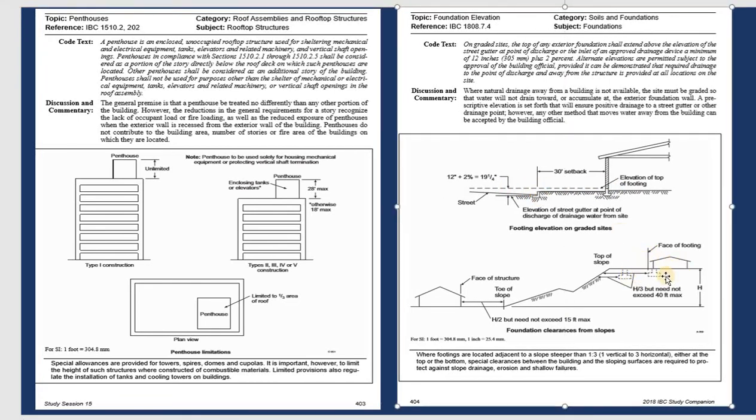If you have the house and face with the footing look like this, and after that we have the slope, and they require a maximum height, that means this house and the other house have different heights like this. You look at H, the different height between this house and this house, and they have a slope from the first one to the second one. The distance from the setback they need to count from the face of the footing to the slope.